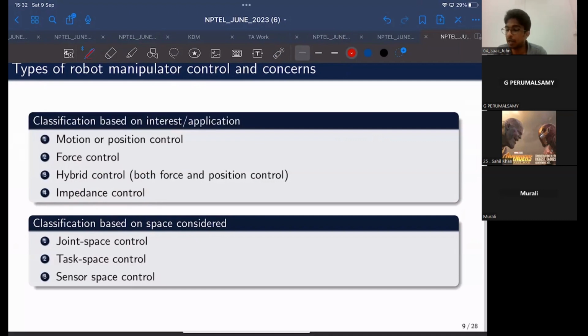So if you are only using force control, and the robot is not interacting with any objects, it'll move very fast. That is basically not a good thing to have, because in the absence of a force, if a robot is moving very fast, there is a high risk that it can injure something that comes within its workspace. Whereas if we go for impedance control, it won't be like that. If it encounters an object, it will try to comply around this object.